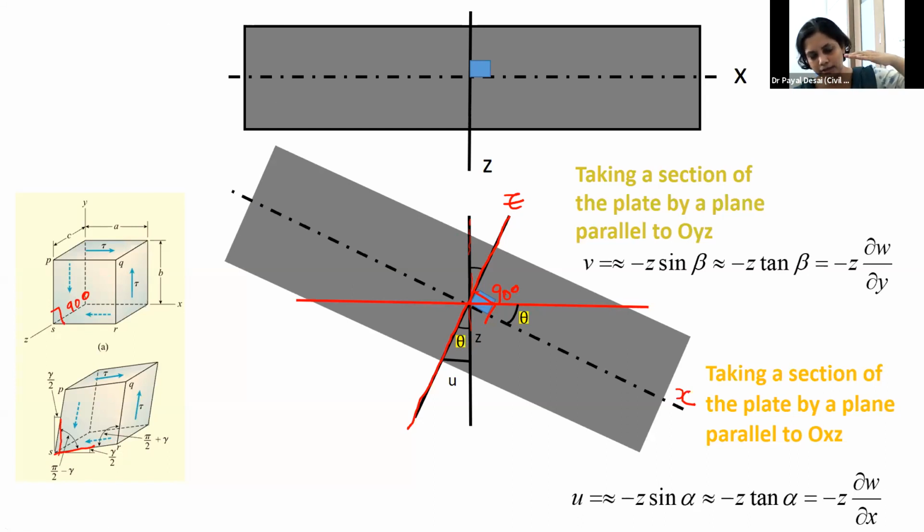So when you apply any shear stress on this particular cube, this angle of 90 degrees does not remain 90 degrees at all. It is lesser than that. That means the effect of the shear stress, and the effect of the shear stress is shear strain. The two sides do not remain at 90, there is some distortion, a change in the angle, and we may call it that the body is subjected to shear strain.